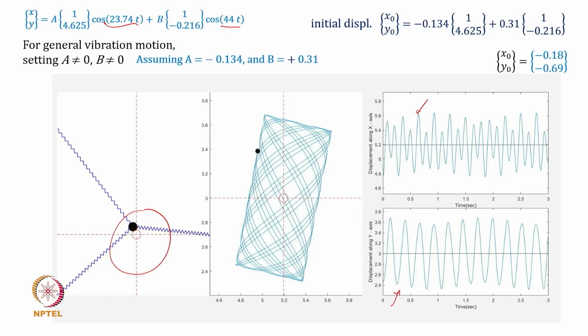but it's definitely not a harmonic motion that you can observe in x and y both. So, this is a typical response that you get if we disturb this 2 degree of freedom system with an arbitrary initial excitation or initial perturbation x naught y naught, which is not conforming to either the first mode nor with the second mode, and therefore both of the two modes contribute, and this kind of a motion is observed, which is going to happen because the two frequencies are not commensurate.